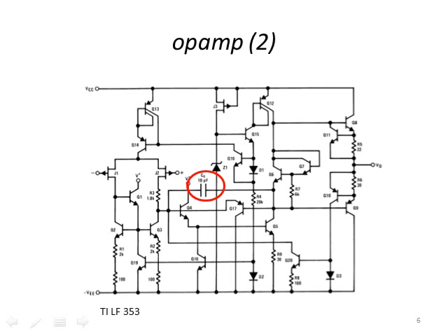This is an example of a bipolar operational amplifier with JFET inputs. On the previous slide we saw a bipolar junction transistor. Those are usually very fast. They consume a lot of current, but they also have a lot of input current associated with their input terminals, which is not always what we want. In this case, we compromise and we make a bipolar junction transistor operational amplifier with JFETs at the input, so we have very, very low input currents to this system.